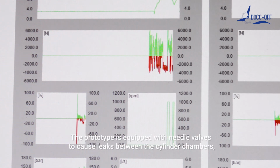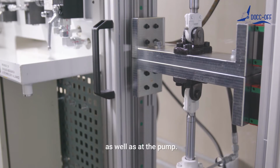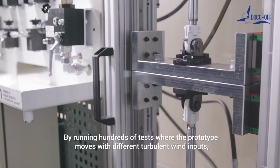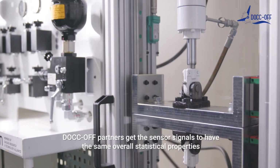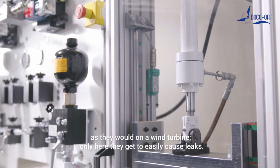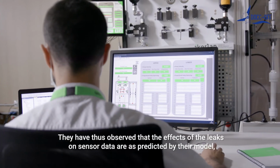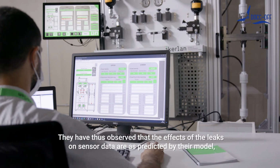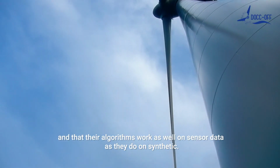The prototype is equipped with needle valves to cause leaks between the cylinder chambers, as well as at the pump. By running hundreds of tests where the prototype moves with different turbulent wind inputs, Docc-Off partners get the sensor signals to have the same overall statistical properties as they would on a wind turbine. Only here they get to easily cause leaks. They have thus observed that the effects of the leaks on sensor data are as predicted by their model, and that their algorithms work as well on sensor data as they do on synthetic.